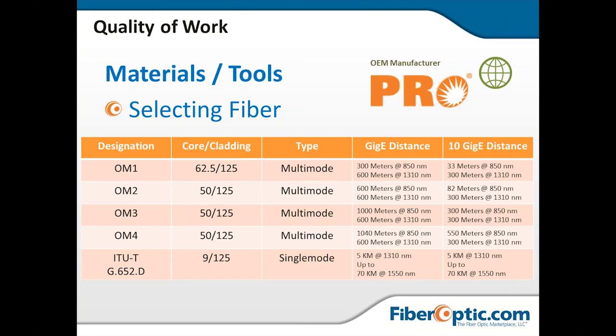So what we're able to do with the VCSEL is, with the 50 micron core, it's a very small core compared to the 62.5, so we needed a more narrow spectral width to launch 100% of that energy or power or light into the fiber optic core. The reason that we as a nation had the 62.5 micron core years ago was that in the LEDs, the spectral width was very wide.